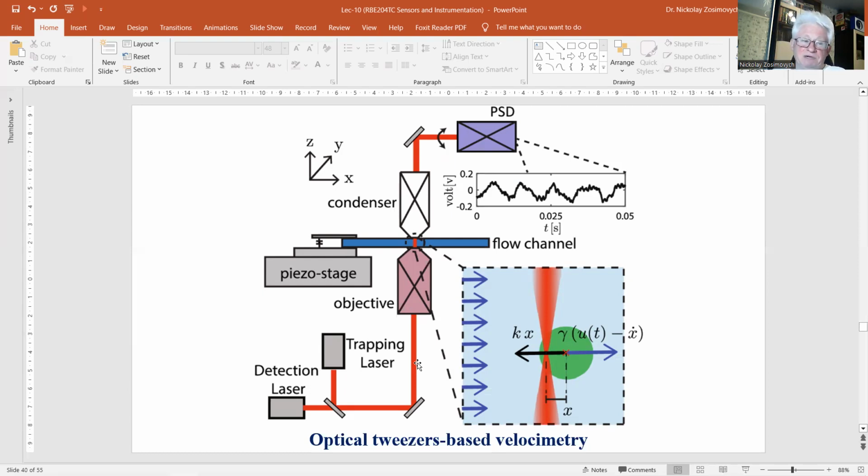The grating has been replaced by a CCD camera acting simultaneously as detector and spatial filter device. Information about the direction of the movement is obtained by creating a quadrature signal, which is simply accomplished by a modified CCD readout system. Experiments reveal velocity errors of less than 0.1% up to velocity of 20 meters per second.